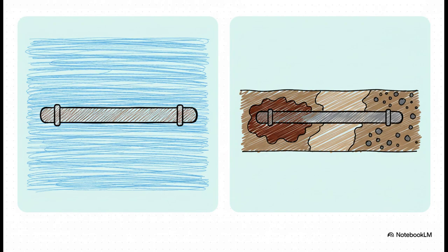Now, here's a fantastic, kind of counterintuitive point that makes for a great exam question. You'd think that a pipeline sitting in the open ocean would be in the worst possible spot, right? Well, yes and no. Saltwater is very corrosive, but it's also very uniform and predictable. The real nightmare is on shore, where the soil can change from clay to sand to rock every few feet. This creates all these tiny, different environments, leading to unpredictable corrosion hotspots that are incredibly difficult to manage.